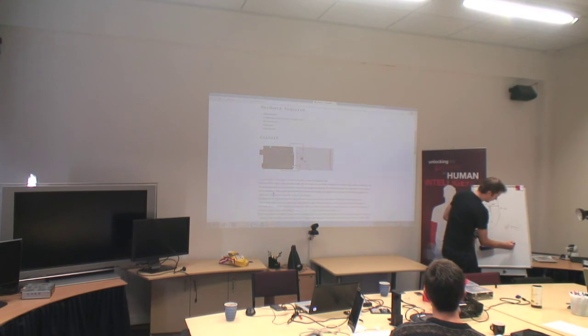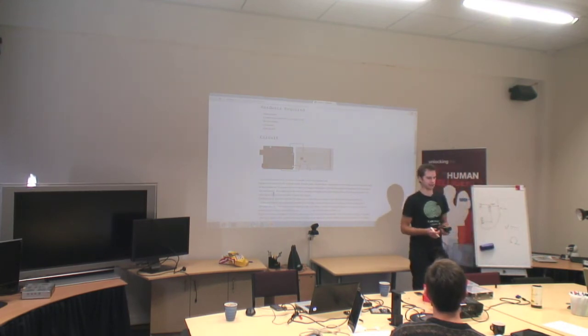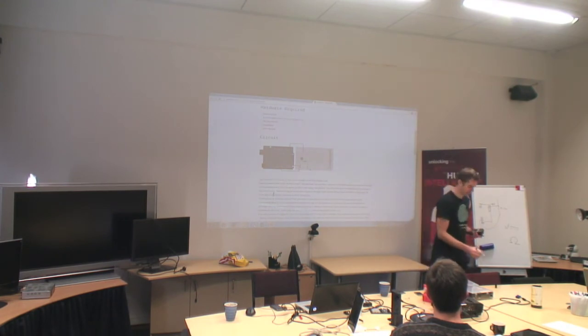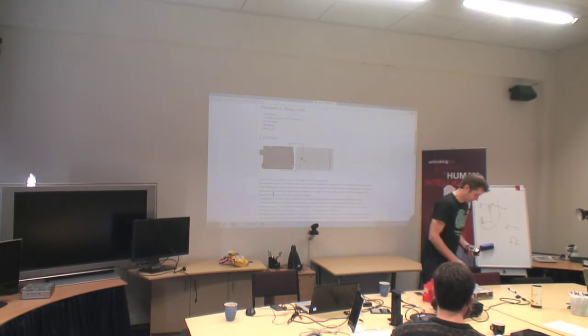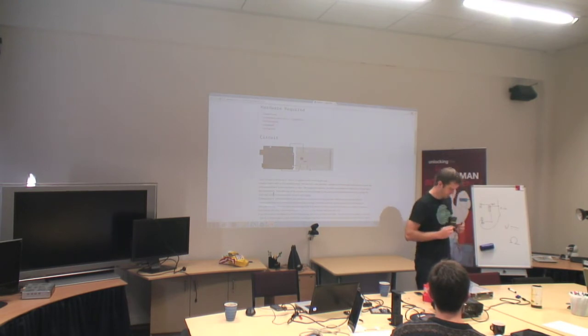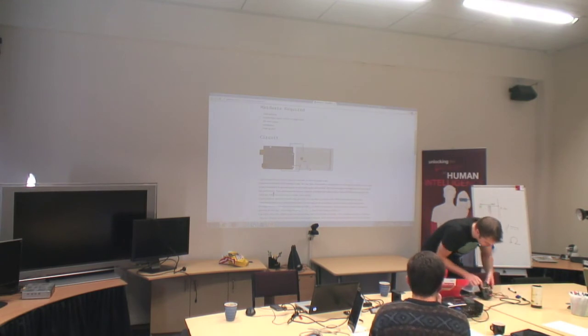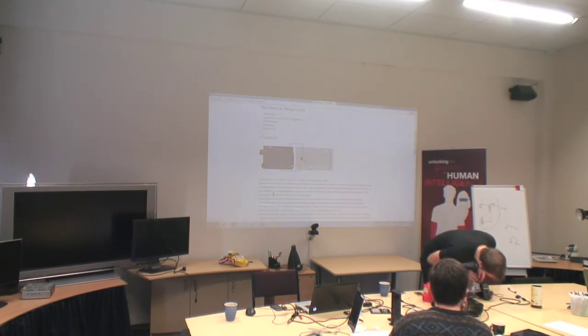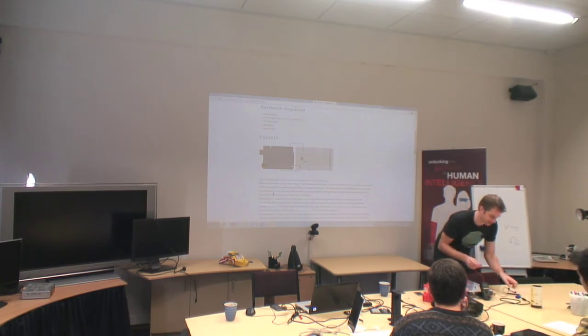Then we have the ohm symbol, which is resistance, which is actually what I was using, and basically measures how much resistance there is between two objects. So for my switch, I did two things. If I can somehow prop this up so you guys can see it. Right now you see I'm measuring voltage. If I do resistance, you see it says 0L, which means that basically there's an infinite amount of resistance, so there's no connection.